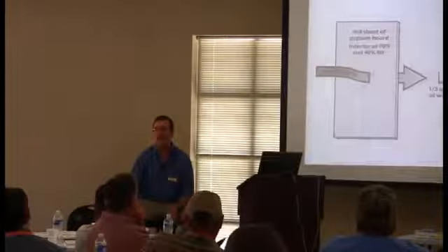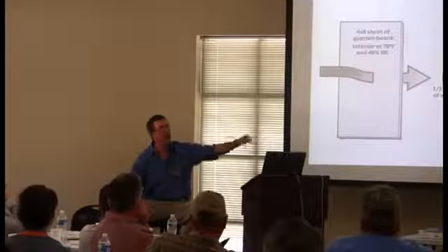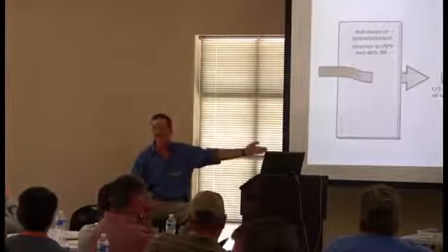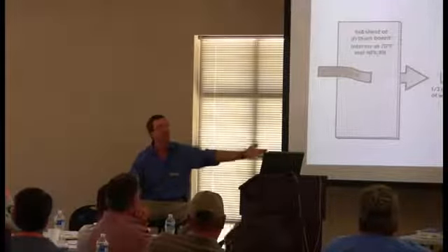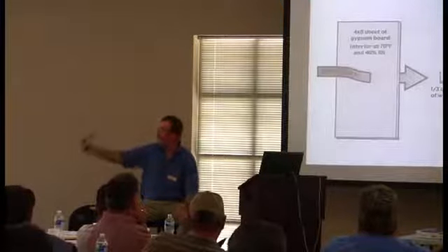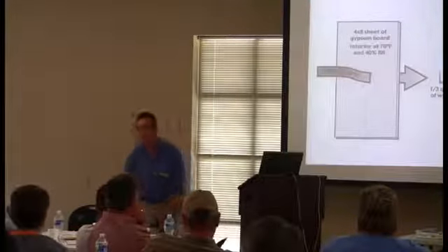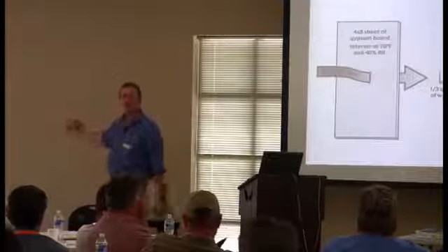And in Canada, it's a one-way climate, right? It's always cold outside. It's always dry outside because cold air is dry air. And inside, it's relatively humid. So that water vapor tries to transport or diffuse through the wall. So they would put a vapor retarder on the inside of their wall, on the warm side of their wall.